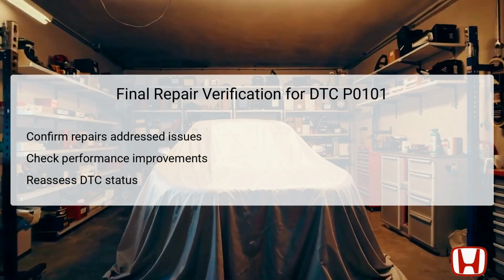The final repair verification step is crucial in ensuring that all preceding troubleshooting efforts and repairs have addressed the root cause of DTC P0101 effectively. After clearing the DTC and performing necessary repairs, it is essential to evaluate the vehicle's performance under typical driving conditions.